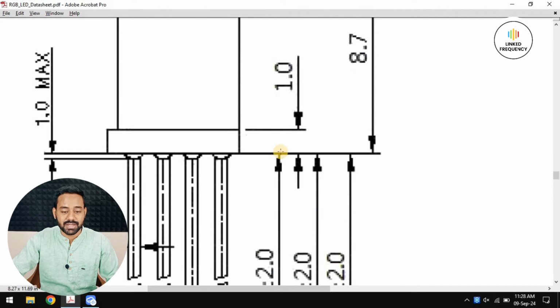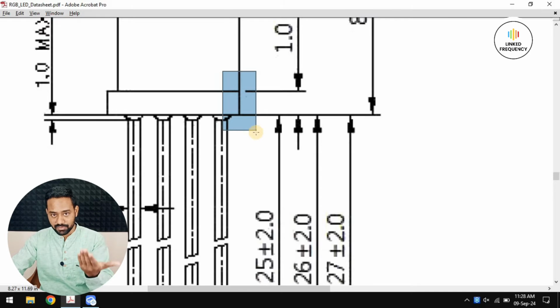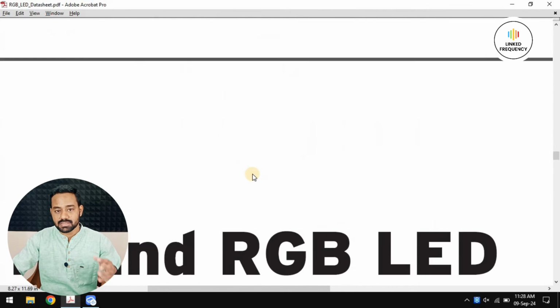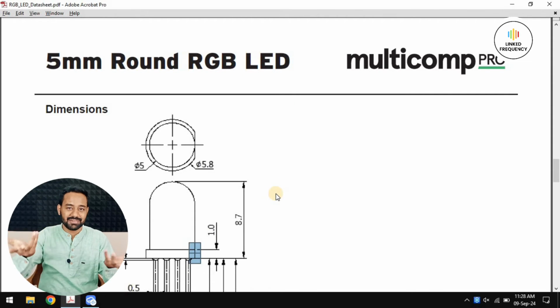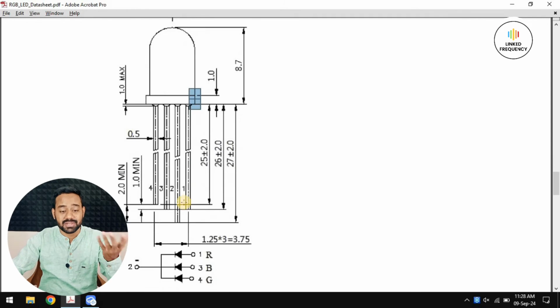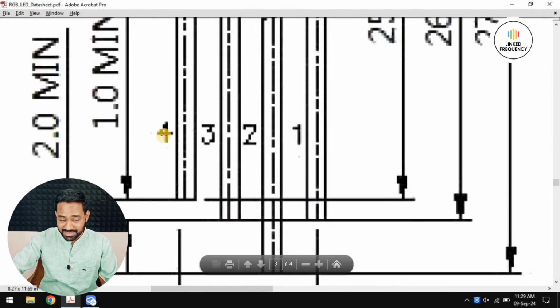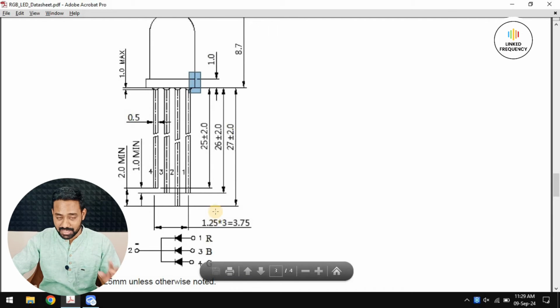Why? Because if you scroll a little bit down, you can see here the cut part of this particular LED indicates the notch from this viewing angle, and that is the first pin of the LED. And the first pin of the LED is the R pin actually, which is the red color pin. And if by mistake you assume all are 4 pins, so if you insert it like this or like this, everything is the same. If you assume like that and make the first pin the 4th pin, because that is how our numbering system starts, 1, 2, 3, right? If you misunderstand this one, then your entire LED is not going to work on the PCB when you solder it. Why? Because it's wrong actually. The cathode is not connected to cathode, anode is not connected to anode, then it doesn't light the LEDs. So that's why we need to understand where the first pin is. That is the first process.